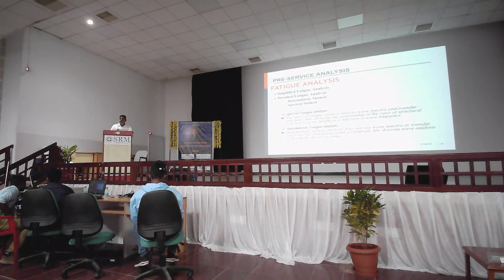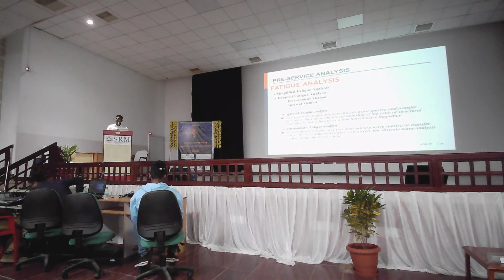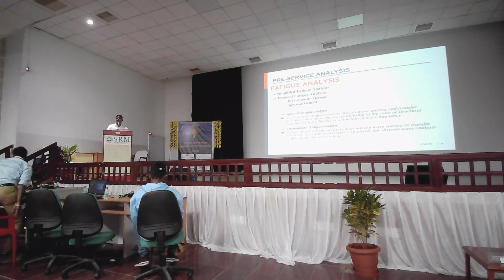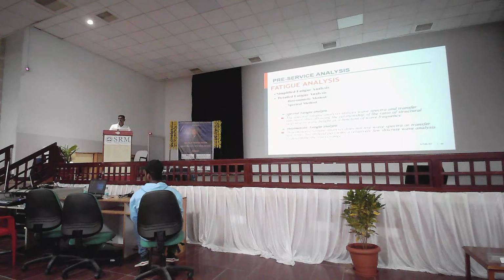So the fatigue. For fatigue, we need to fix whether we need to go for detailed fatigue or whether simplified is enough or not. We have to calculate our natural frequency of the structure. If our period is more than 3 seconds, definitely we need to go for spectral fatigue because the probability of fatigue failure is more. So we need to calculate the spectrum. We will get all the wave and environmental data, all meteorological data we can get. Anyway, without the data we can't design.